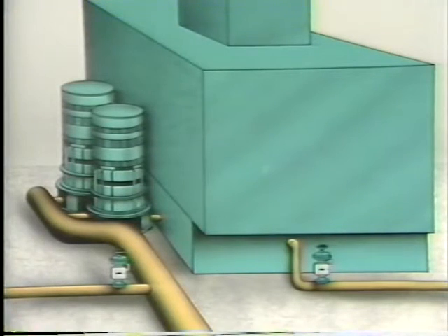This illustration represents part of a condensate system. In the system, steam that has been used in the plant is directed into a condenser, where steam is condensed into water, or condensate. The water collects in a hot well, which is this tank located below the condenser. Two pumps draw water out of the hot well and pump it to various processes in the plant.